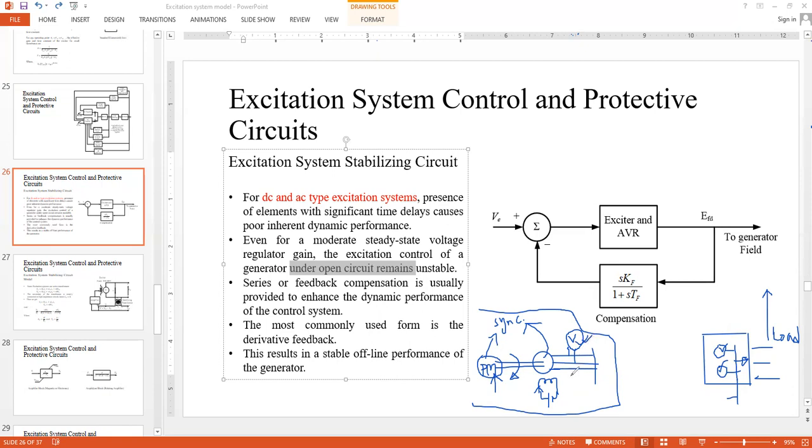You have to check the phase sequence. You have to check the frequency. Of course, the frequency is checked here because it is running at synchronous speed. So there are actually four conditions before you can bring the unit online and connect. Let's say if there is a switch, then you can close the switch. This is known as synchronization of a unit.